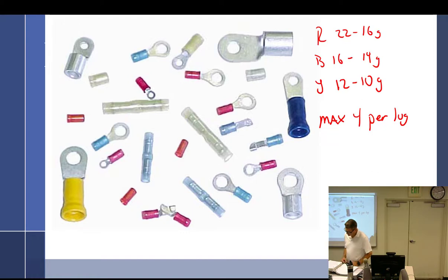I seem to recall reading somewhere that there's something about do not solder terminals. That is not a good idea. Man, all the good avionics shops insist on it. Yeah, I can't remember exactly where I read it. Yeah, one of the Q&As does say that. It just says crimp only. Yeah, it's crimp only. Wow. I don't have a problem with crimping. Wonder if that's because of safety equipment.